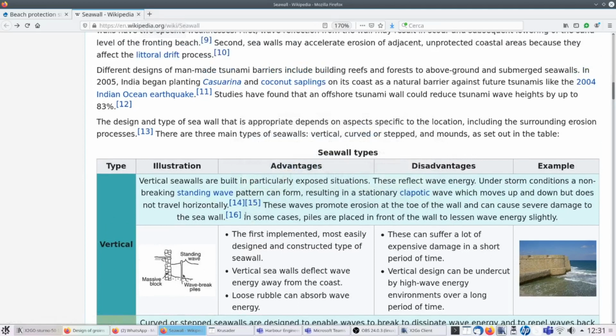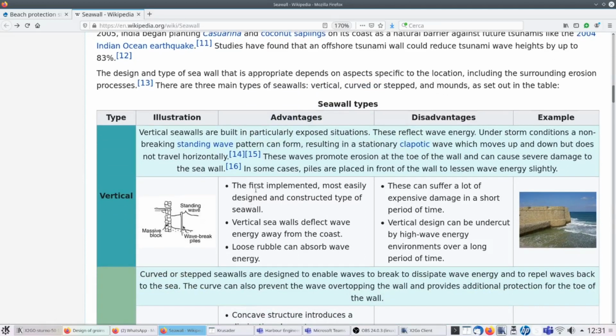Okay, I'm not discussing the design of seawalls. There are standard procedures for determining the forcing of waves against seawalls. Basically, you take the energy of the wave and you convert this energy into an action, because when there is the impact between the wave and the seawall, you get a conversion, a transformation of the energy flux of the wave into a forcing against the seawall. And there are suggested procedures to compute this forcing.